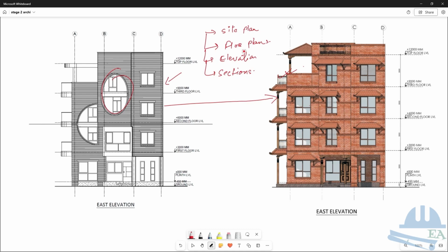Also in this architectural plan, you can see a basic furniture layout. Normally what people do is that if the budget is low, the basic furniture drawings are made within the architectural drawing, and if the budget is high, separate interior drawings are prepared, for, let's say, how the ceiling will look, how the walls will look, how the floor will look, how each furniture will be designed, and how each furniture will sit in the room or in the space allocated for it.